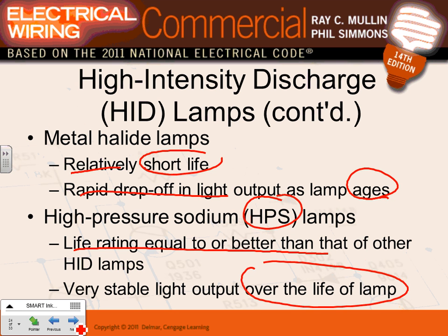When it comes to installing lighting fixtures, guys, you are the representative of the customers. They're going to come to you and say, give me the best product in the market. So I can get you high pressure sodium, metal halide, or LEDs. LEDs are the best for us, but if you don't want to pay for the LEDs, high pressure sodium can maintain its lamps for 24,000 hours or so or higher, and it maintains the same amount of light.